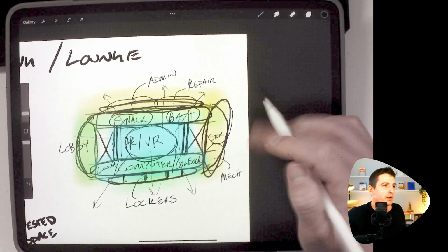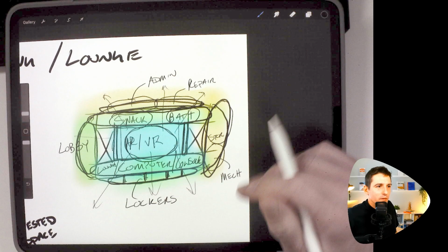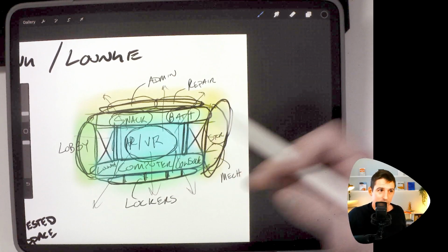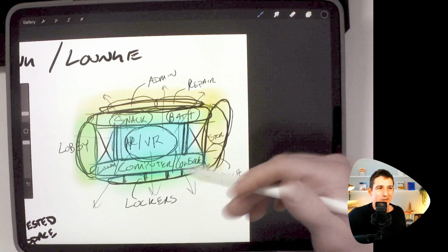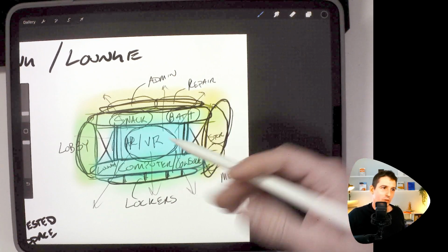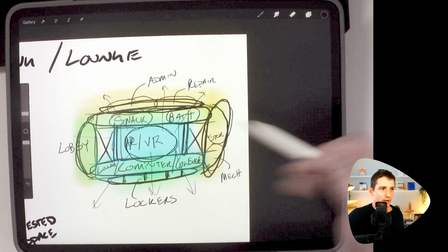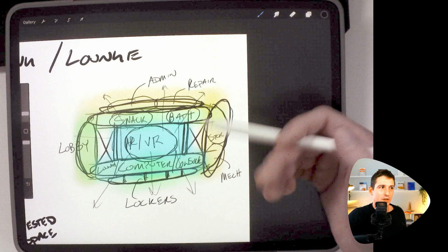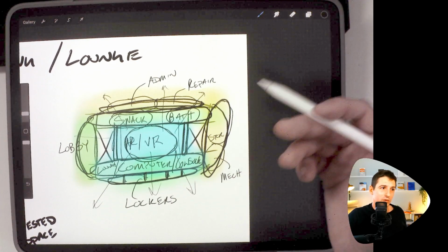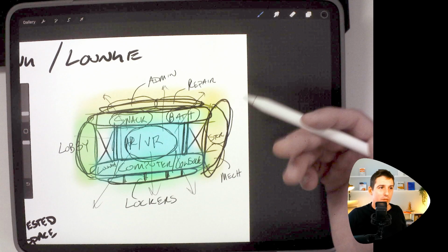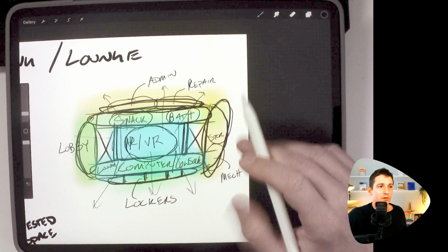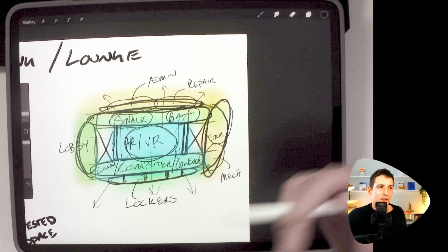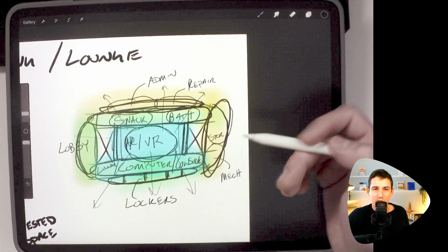So as you think through it, right, you just layer in more information, think more practicality. That's what I did here. I was thinking about adjacencies as I subdivided these zones. And when I made the zones, I was really kind of thinking big picture. How do I maintain my views? Where am I coming into the building? What are some of the first things I need to see as an end user? What are some of the things that I need to have available to me as an administrative person, someone who's working there? And so you have to just consider all aspects of who's using the building, what they're going to be needing, and in the program, what needs to be near each other.